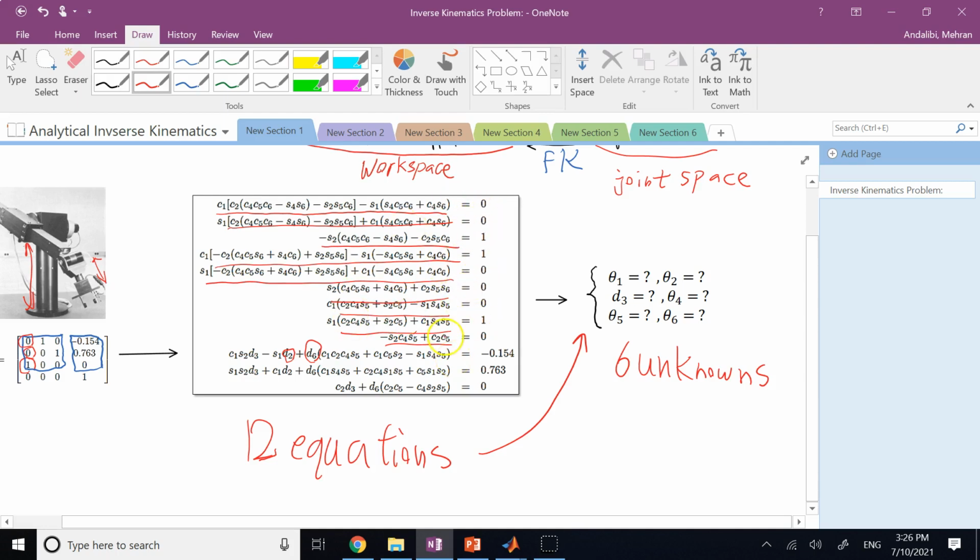A rotation matrix has a magnitude of 1, and the columns are perpendicular to each other, but writing those constraints means, for example, that I have to consider the first 3 guys as a vector, then the next 3 as another vector, and then say the dot product of them is 0. So those constraints, if you want to add them, are even scarier. So first of all, the system is over-constrained. If it was a linear system, you would have to use the pseudo-inverse and find the least squares solution or something. Right? So does it mean that you cannot find the exact solution?